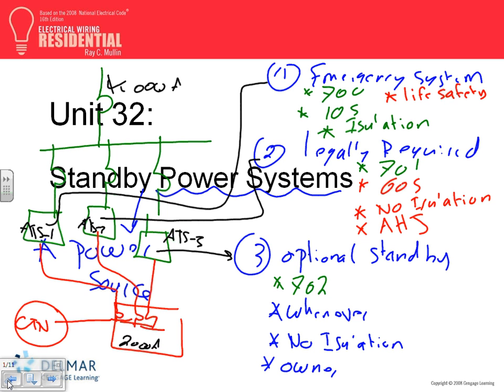We will leave the details to later, guys. Now, this book, Spencer, concentrates on only one system at a time. But you can think of all these systems as being grouped together. Any question, guys, about that? So we have 3 systems. I can feed them from 3 different generators, or I can group one generator through a switch gear and feed each one of these systems through auto transfer switches. For example, Brad, auto transfer switch number 1 has to transfer within 10 seconds.